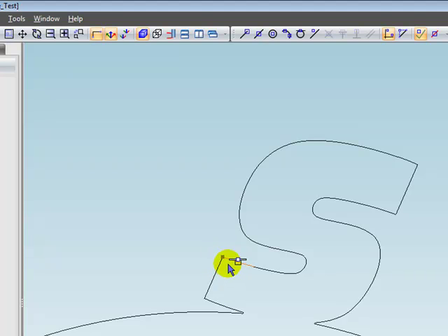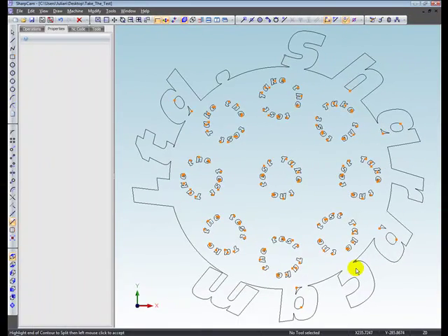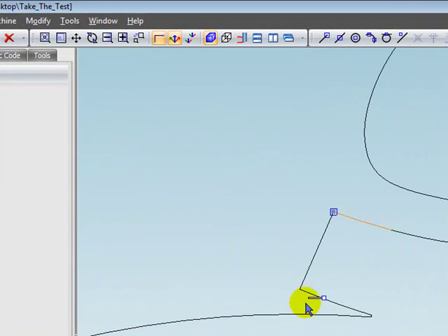And you can see this contour has clearly changed into an open one. If I zoom all, that obviously was the start point, so it's now been broken into two contours, two open ones. I might want to split it there as well, so now effectively it's back to the original line.